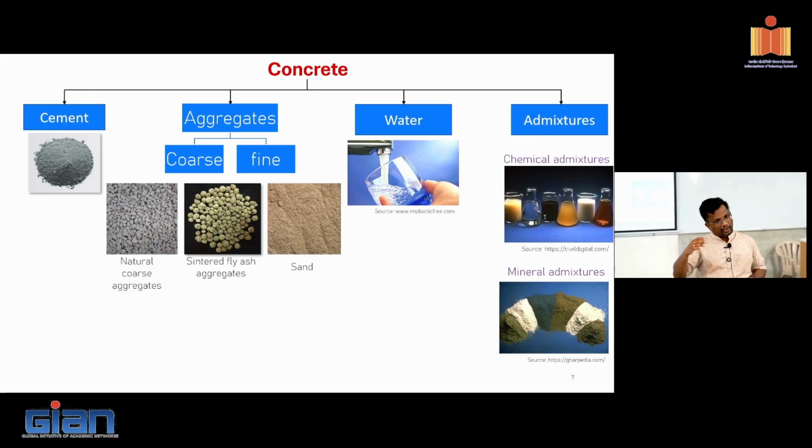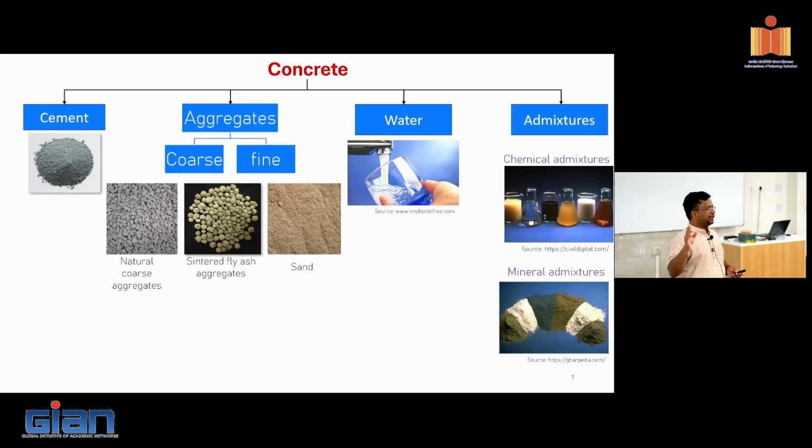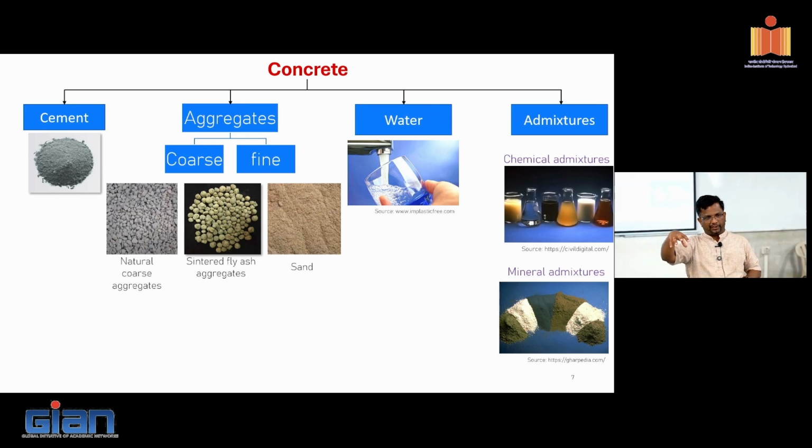So this is a very, very important factor. Even in an RMC plant, if you are the client and you want to verify how good the concrete is, the first thing you need to do is check the quality of the water they're using and make sure it is within the permissible levels of chloride. Otherwise, if chlorides are there in the system, within 2 years, in fact, we have several buildings in the NCR region close to Delhi, though it's a very dry region, nowhere close to marine conditions, right? Still, a lot of buildings have corrosion issues because they were using groundwater which is full of chlorides. So that's one thing that we need to be very careful about.